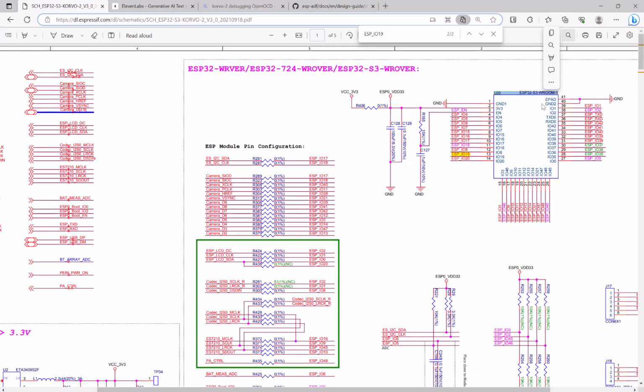These pins, GPIO19 and GPIO20 on the ESP32S3, are used by USB_D- and USB_D+ to provide two USB channels, one for JTAG and the other for the USB terminal connection to monitor diagnostic messages.